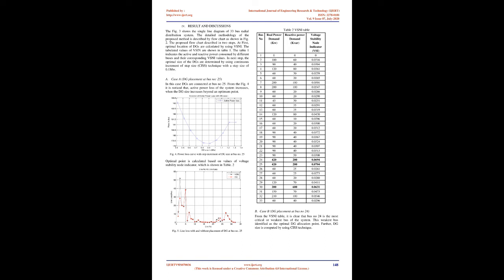The equivalent load current injection corresponds to the power injection equations. 3. Proposed methodology. In a distribution system, the node voltage plays an important role in maintaining good voltage regulation. Ideally, voltage regulation should be nearly equal to 0, but due to line resistance and reactance there are slight drops in voltage at different nodes of the RDS.